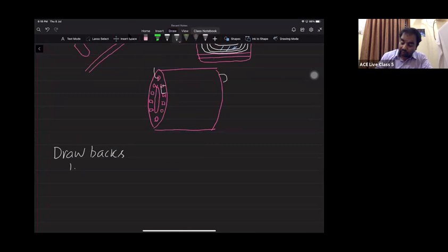Like that, conductor to conductor, you have to place the conductors. So here the winding procedure is complicated. But in case of open slots, it is easy. In case of semi-closed slots, it is difficult, but here it is complicated. Why? Because we cannot see the slots from inside. We can see the slots only from the side. Is it clear? Confirm me.